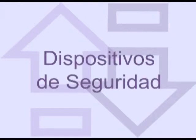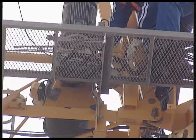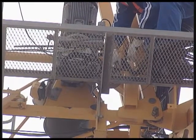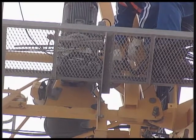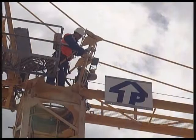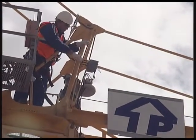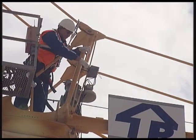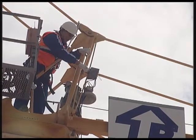Safety devices. Overload limiters. Load limiter. Safety device that prevents lifting loads heavier than the maximum permitted by the crane, either at high or low speeds. The device operates when the nominal maximum load permitted is exceeded by 10%. Load moment limiter. Safety device that prevents lifting or moving loads that exceed the nominal momentum of the crane.